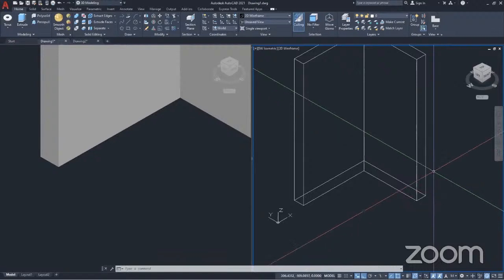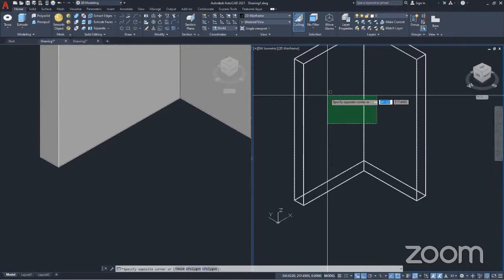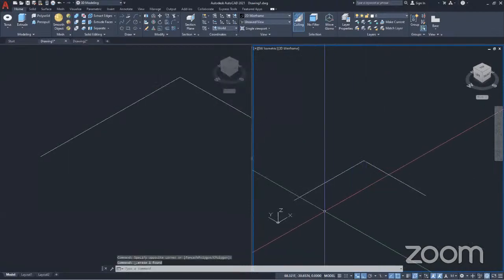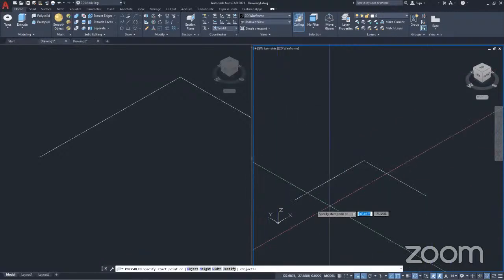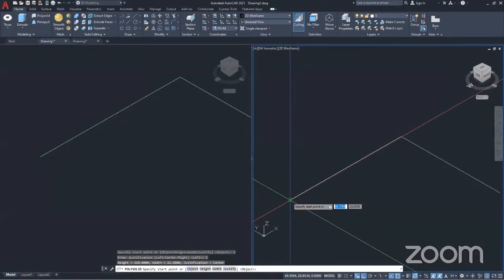Okay, I think I'll have to repeat that. Now you click on the polysolid. Now we use the justification, the left justification, not the right. Okay, this time let's use the center justification so you see the difference. I want to use the center justification this time. And then I start drawing my polysolid.